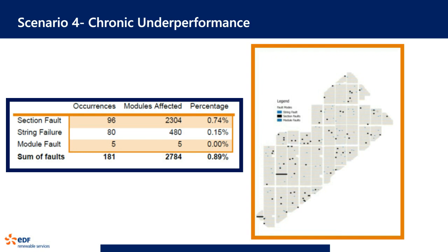However, by doing this, knowing that we were 100% physically complete in producing on the plant, we were then able to go back, which took a lot of time. Again, don't think this was an easy process. We went back and recalibrated the model down to the individual input level, so that we could say this input is reading 0.5% high, the CT on a string. The normalized inverter ratio is such that this inverter seems to outperform that inverter, all other things aside, by 0.25%.